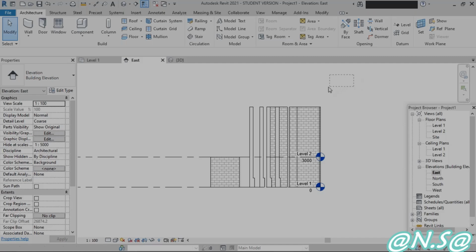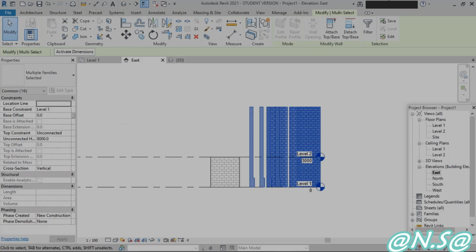In the cross window selection, we have to draw the window from right side towards left side. We have to drag this window from right side towards left side like this. If you can observe, what is the difference here? Can anyone tell me what is the difference? I'm just dragging this from right side toward left side. Apart from that, did you identify anything? Yes, total objects are selected, ma'am. All objects are selected.